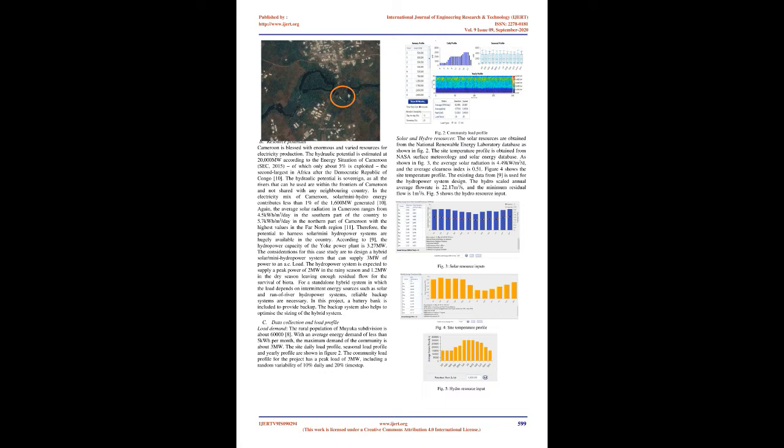In developing countries without infrastructure like Cameroon, microgrids are more likely to be cost-effective since the installation cost must be compared with that of installing high-voltage transmission lines. In the grid-connected mode, the system voltage and frequency are fixed by the primary grid. In island mode, keeping demand and supply balanced to maintain voltage and frequency is a huge task.